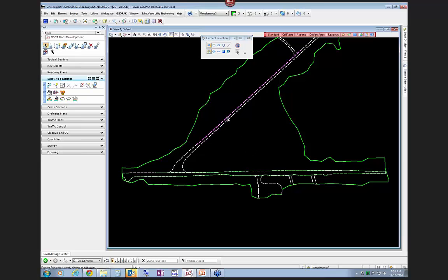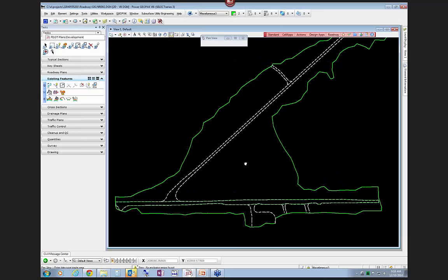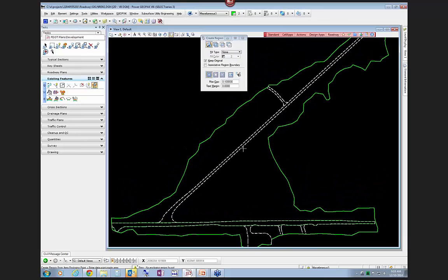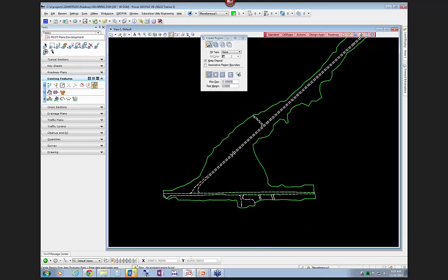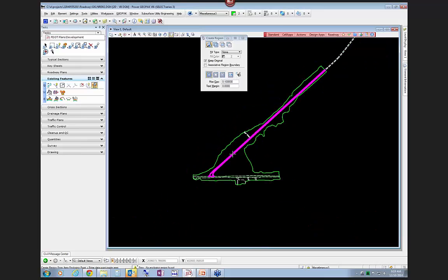If I do the same thing here, go ahead and select the tool again and select in this area, you'll notice that I get this error, no enclosing region found. And that's mainly because I don't have the entire area within my view. That's a little issue. So if I just hold in this area with the cursor and then roll out till I get the whole view, and then click in it, it will actually pick up the shape. You just have to keep your mouse steady, and then it will basically build that shape.